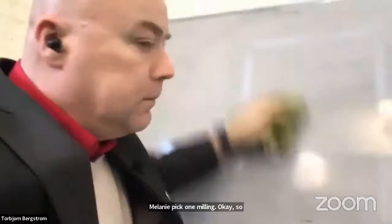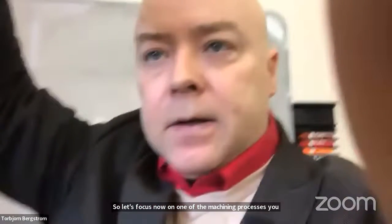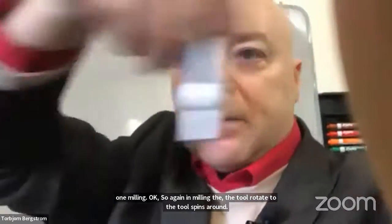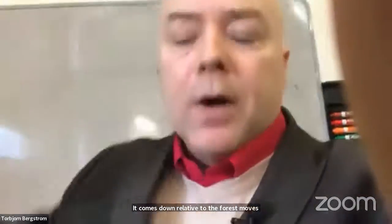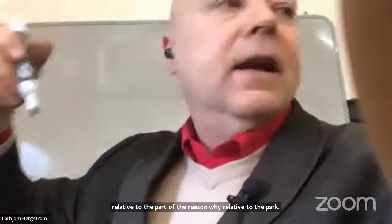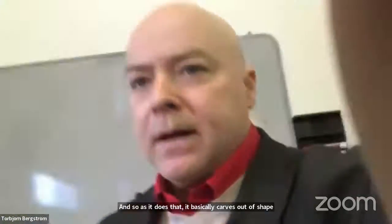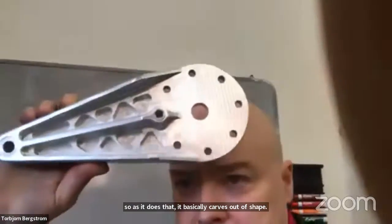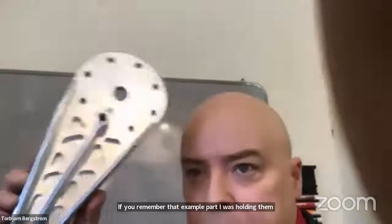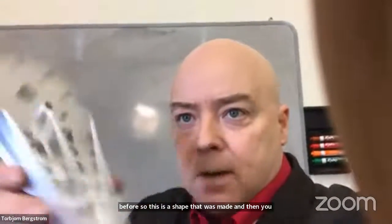So again, in milling, the tool rotates, so the tool spins around. It comes down relative to the part, it moves in X relative to the part, it moves in Y relative to the part. And as it does that, it basically carves out a shape. If you remember that example part I was holding up before, this is a shape that was made, and you see it's got a slope there on the top.